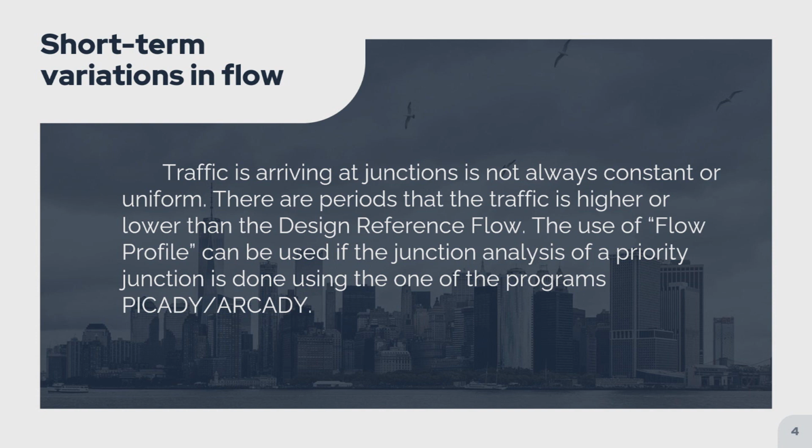A typical profile could involve the inputting of peak time flows in 15-minute intervals. When calculations are being completed by hand for a priority junction or roundabout, such short-term variations may be taken into consideration by utilizing an hourly flow equal to 1.125 times the DRF.